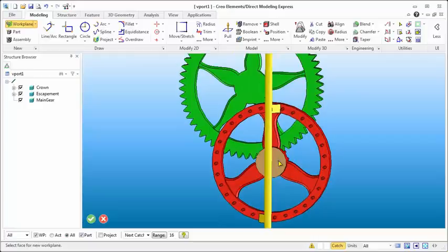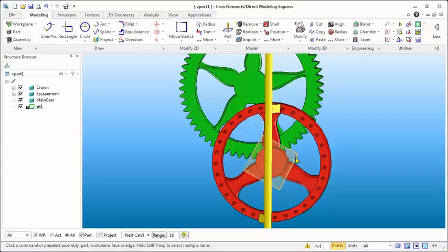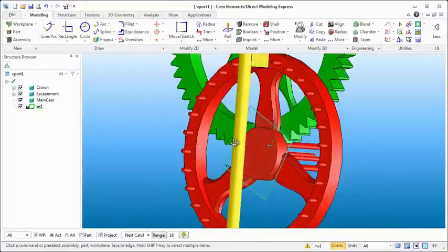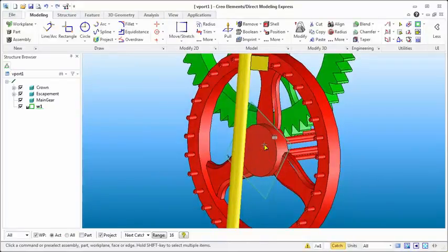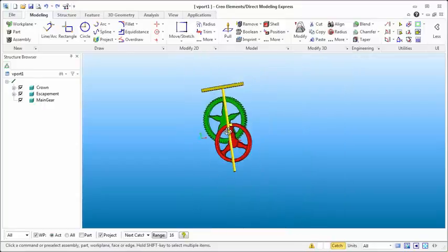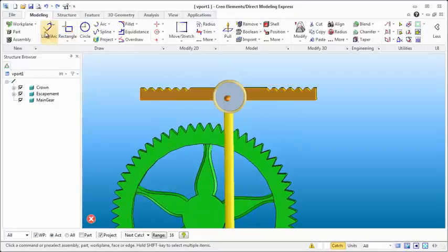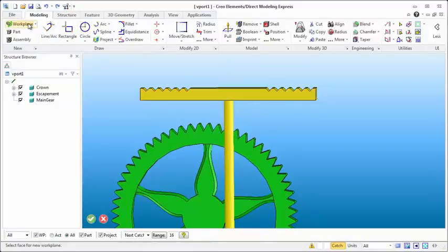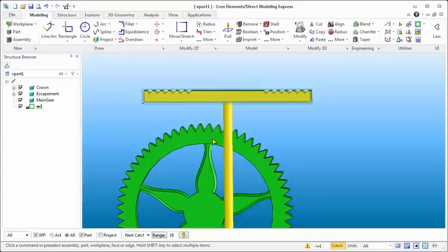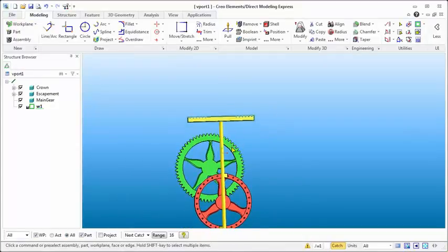Now, you remember in one of the previous episodes I had rotated some of these gears, and you'll notice when I create the plane, it actually orients itself according to the orientation or the rotation I did here. Now this can be a bit of a problem. Let's say I want to throw in a crosshairs on here, and you'll notice that the crosshair now is at that angle as well. So instead of trying to reorient everything and make sure that everything is going the way I want it to, I can grab different geometry for the work plane on the face, and I'll do this one. That way I have everything squared up the way I want it to be.